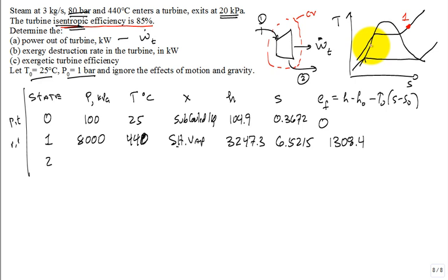And what we want to do is consider isentropic expansion through that turbine first. So it's going to expand on a TS diagram straight down. True? And that'll go to state 2S. Is that true or false? You like that? So state 2S.